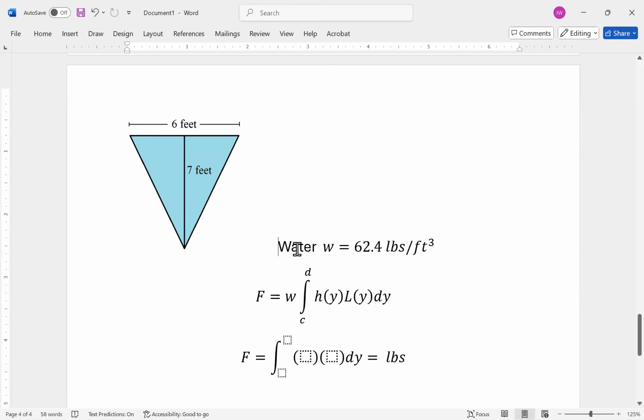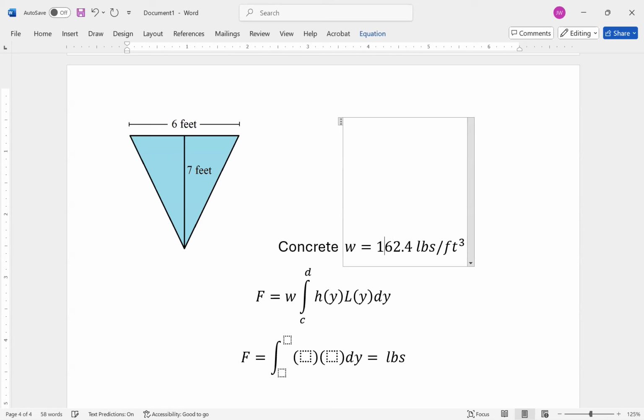Now, once again, obviously same type of calculations, but since we're in feet and the weight density of the concrete we're using is 150 pounds per cubic feet, we're setting it up this way. And I pretend that what I was having in my previous examples as the water line is now the concrete line, so it is the top of that tank.